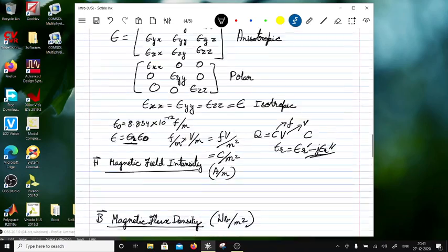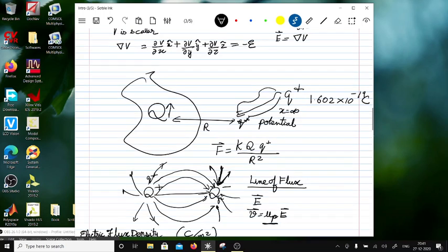If you talk in terms of potential, if you take a charge Q and move it around a loop, then the amount of work you have done is 0, because the net potential is going to be the same. In one case you will be spending energy going closer to Q, and in the other case you will be losing energy. So the net energy gained and lost would be zero, the work done would be 0. This is Kirchhoff's voltage law.